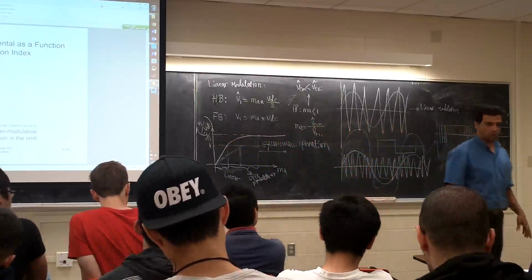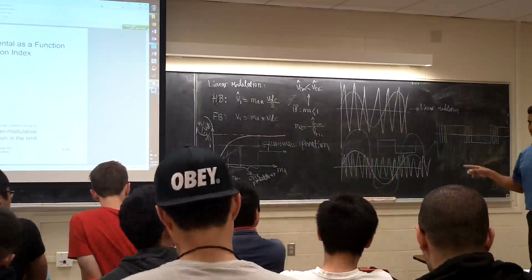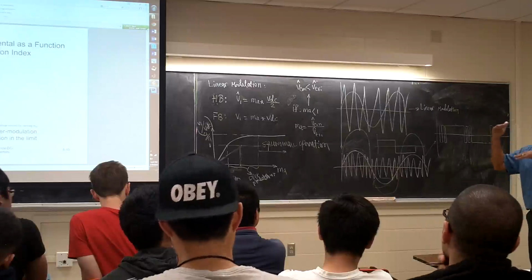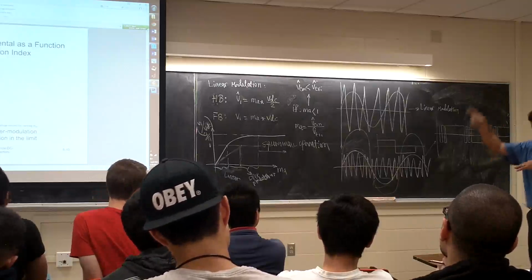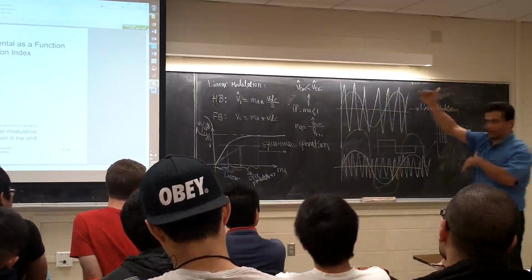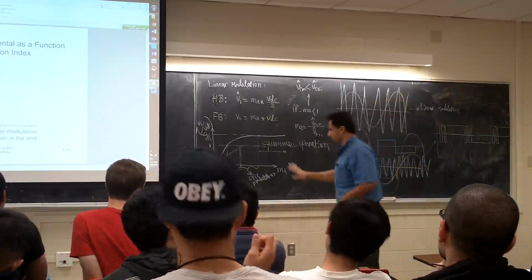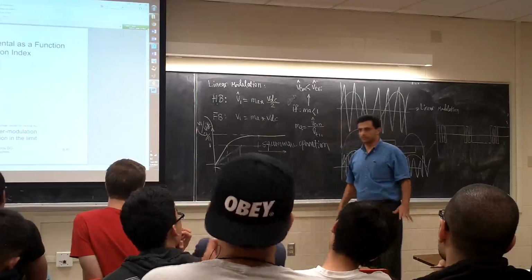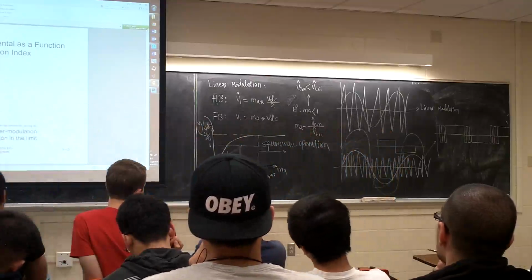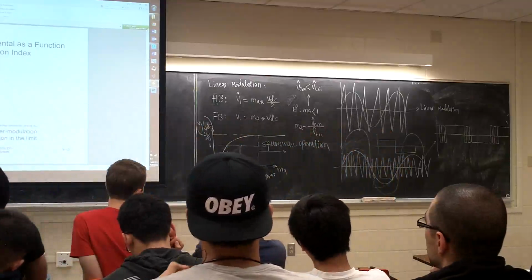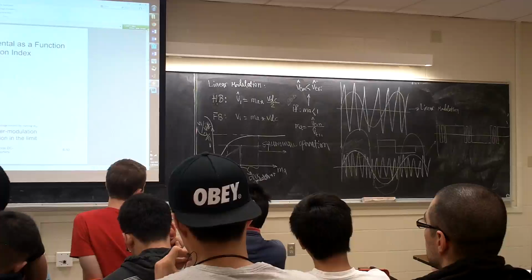And you will see later in the control part you are going to design, I will ask you to limit the maximum and minimum of MA to plus 1 and minus 1. Right? Because MA is like this, you're going to be 1, minus 1. We say to keep it there to not pass this mode. Any questions here? So we are done with the single phase inverters.